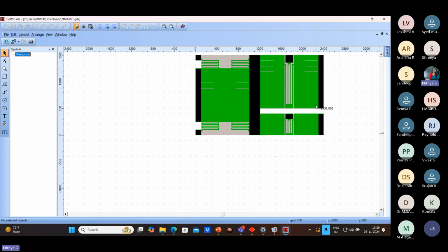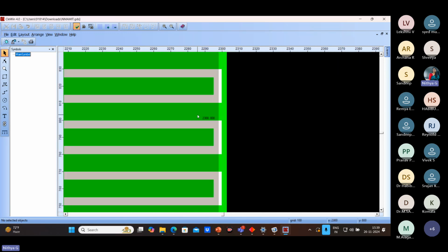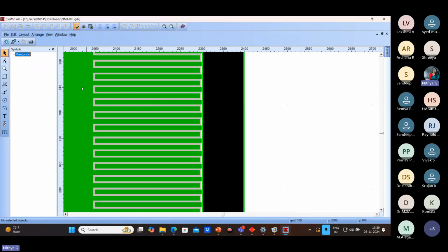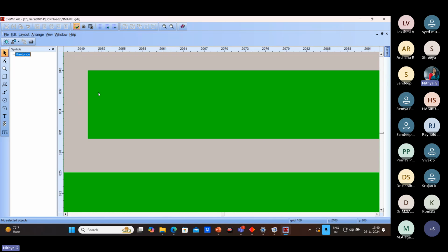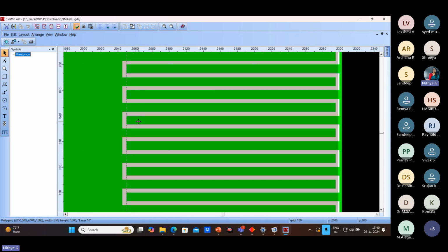Okay, so this entire structure is free to move whenever I apply external force or acceleration. And one more thing I was telling about is the minimum geometry size that is relevant to these fine structures. As of now, they're not much smaller. We can just check. See, it is 842, somewhere around 830, so somewhere around 10 micrometer width. So it is not a problem. I don't have any restriction on the structure or the size, on the length. Only if it is less than 6 micrometer, then I should be careful about the structure.